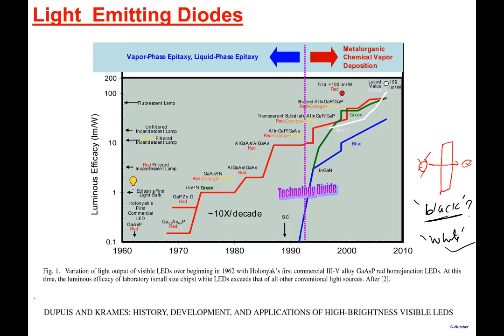Why? Because remember, this light is never switched off. This light is always on behind the LCD. All you're doing is programming the LCD cell to switch on and off, and when it is off, it still allows some light to leak through. And so the black was not very good. So people were always looking for alternatives, and they knew that we have these LEDs. The moment red, green, and blue LEDs became available, they were also thinking, well, perhaps we can integrate them and make a display. But this is where it is a problem.